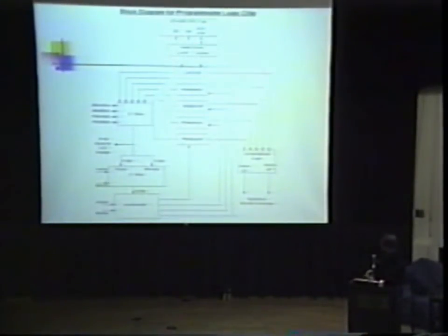This huge circuit is the block diagram of the architecture for the programmable logic chip. Basically, this read circuit right here reads from the clock chip and updates the current time register, which is an internal register. These 4 registers are internal registers to keep the alarm times input from the user. All 5 of these registers then go to this 5-to-1 multiplexer, which chooses one of the registers based on the 4 alarm input buttons. If the current time is chosen, it'll only be displayed. It won't be sent to the next multiplexer.